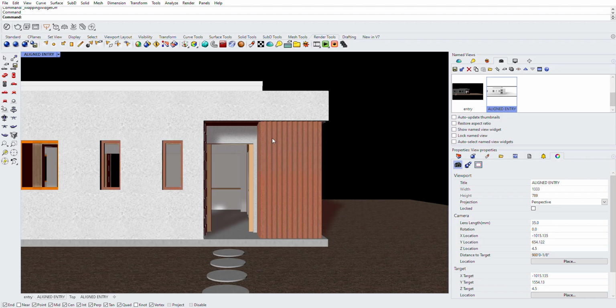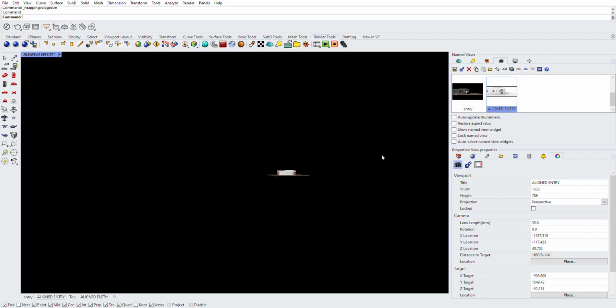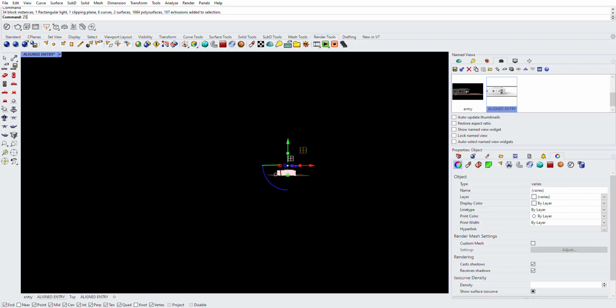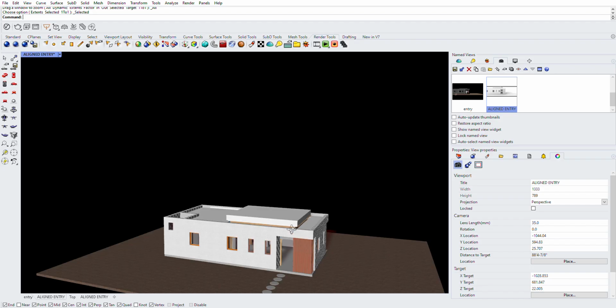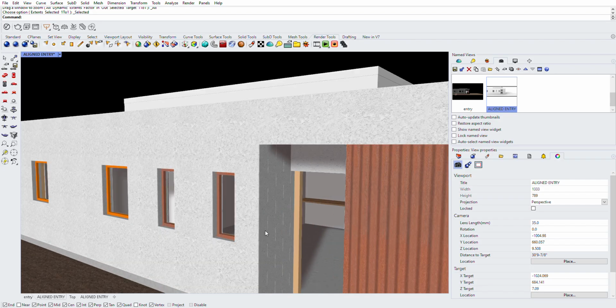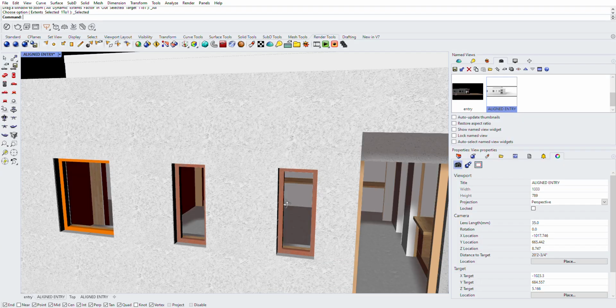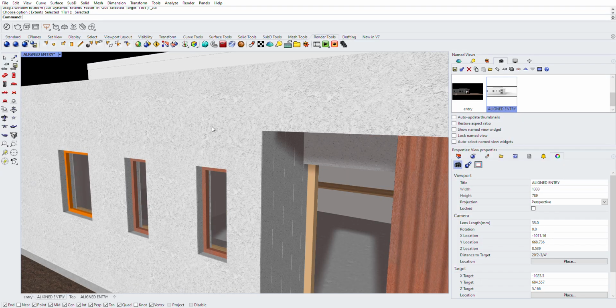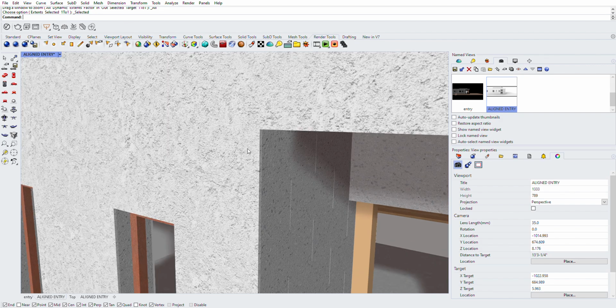Of course, the materials stuff takes a while. You have to set those for, if not objects individually, certainly for broad material groups. So that takes a while to get set up, and it also necessitates stuff like this. If there is a material change, like here I have exposed block versus a stucco finish, you'll notice I had to create a layer of stucco that is able to be its own material.